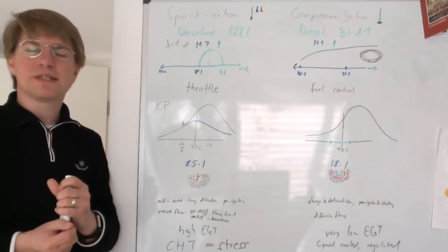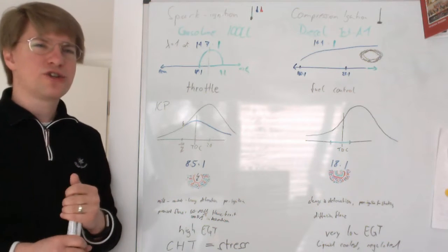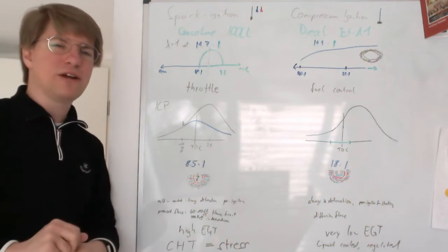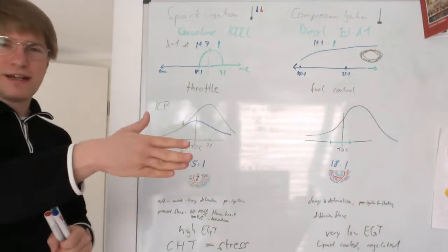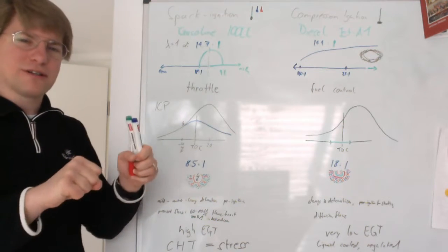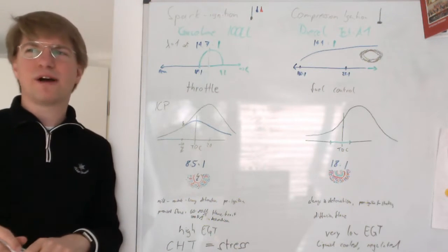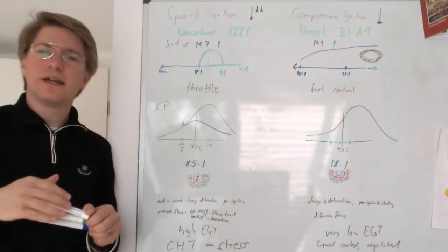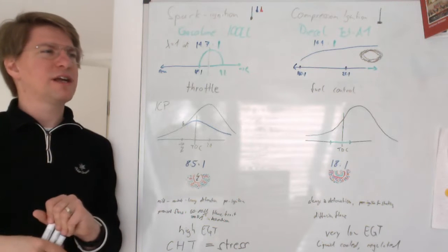And what happens is that some cylinders run richer than others, and when you try to get all cylinders lean of peak, some cylinders will be very lean, others will be richer, and that causes vibration in the engine, and that's why it's often not possible to achieve this lean-of-peak mixture in a carbureted engine.